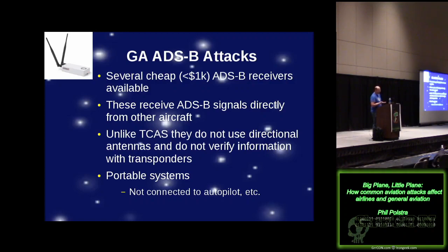I looked at my tablet and said, I would say his altitude is about 2,500 feet and his tail number is N33, because I had it on my display since I was receiving a signal from him. And you might ask, how come the tower didn't know who he was? He was not within range of a ground station where they could receive his ADS-B signal, and they didn't get his transponder for some reason. So things like that happen.